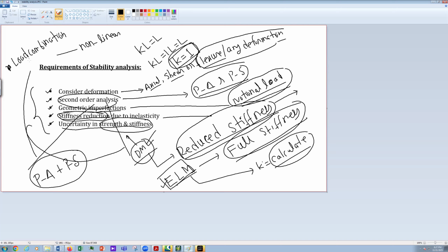You have to make the load combination from linear to non-linear. After direct analysis definition and assignment, first of all, you have to change your notional load factor, which is 0.003 from 0.002. Now your load factor has to be converted from linear to non-linear to account for the second order analysis, which is P delta plus P small delta.